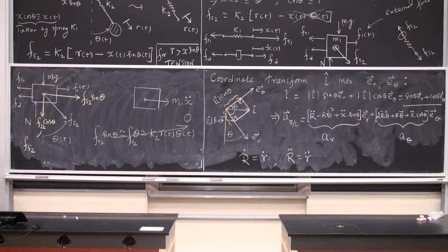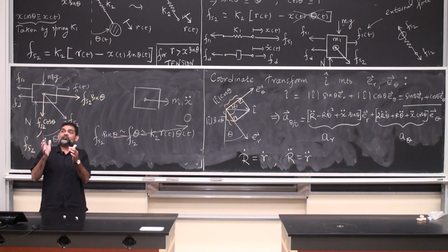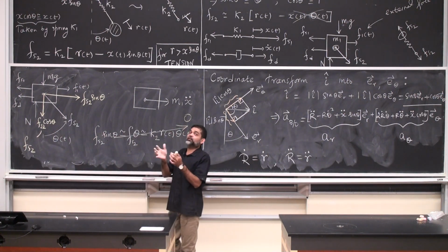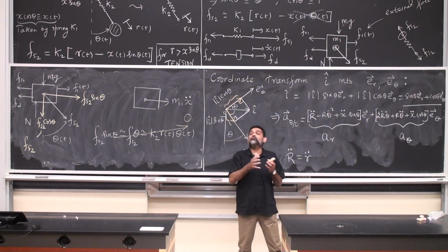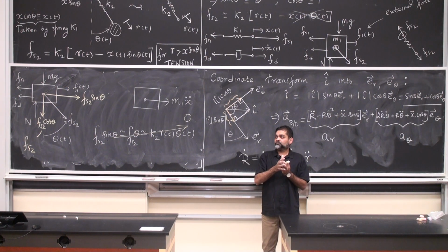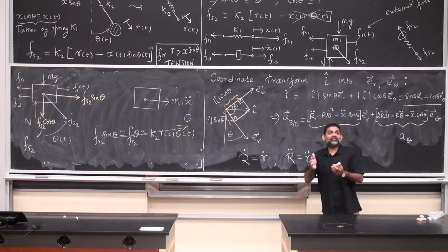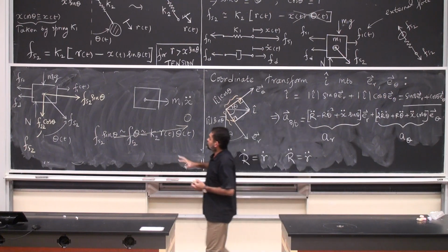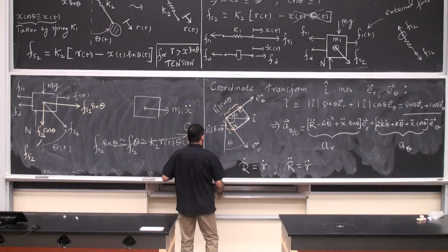Fs2, and you can see now that for small motion, the spring of stiffness k2 is not contributing to the motion of the block m1. This is for small motion, okay, under the realm of elastic deformation. So with that said, I'm going to write the equation of motion for this block system. Then we will go to the pendulum.